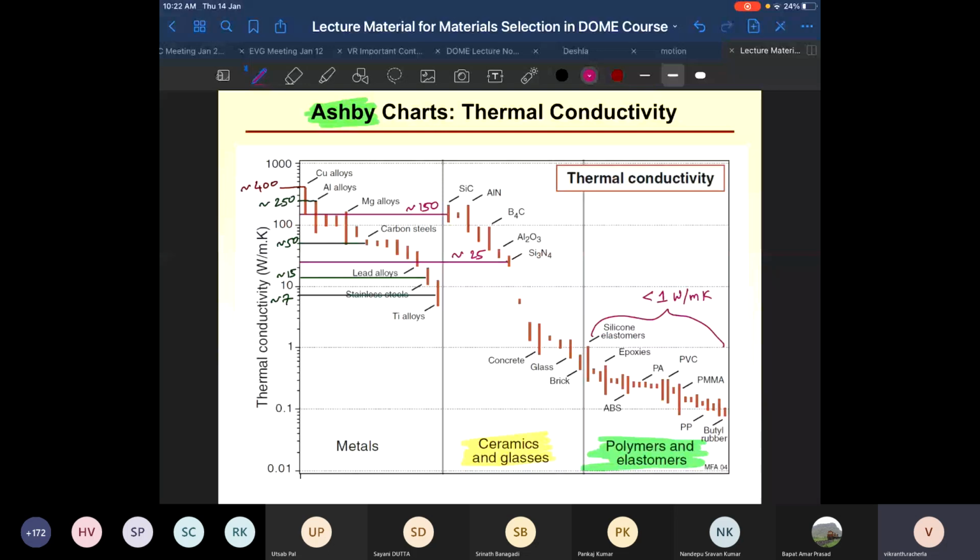What do you think might be a typical efficiency for motors? 80 to 90% is a typical efficiency, particularly for low powered things. As the power increases, normally efficiency also increases. So let's say 90%. What does it mean? It means about 50 to 60 watt of heat is getting generated when you use the mixer grinder.